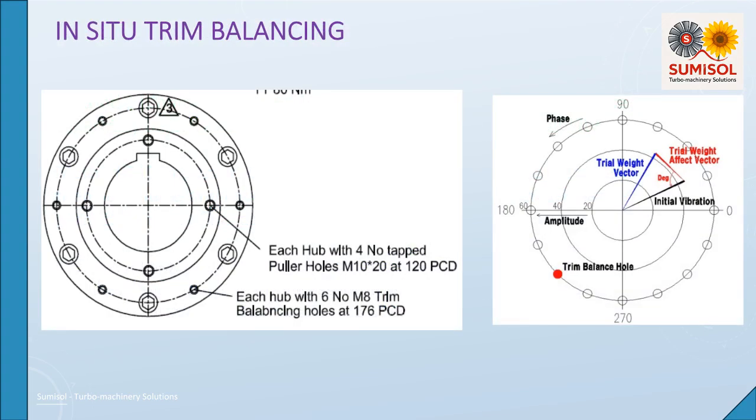When the rotating equipment has high vibration during commercial operation, there are many kinds of root causes to resolve the high vibration issue. In the case of large rotating equipment, it is not easy to perform the complete train test with job coupling and driver at the manufacturer's shop. Then, high vibration by unbalance, which did not occur during the shop test, can be experienced during commissioning due to construction and assembly tolerance and actual operating conditions.